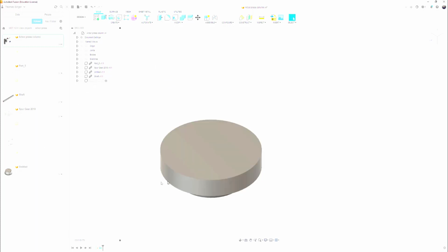So that's the cover plate. Now we have to drill some holes in this cover plate. So creating the holes in the cover plate, I need to put a sketch on here because I'm going to use a tool called the point command to locate the first hole. And that will help us ensure that that hole is positioned properly. So I'm going to do a sketch, put the sketch on the face, and now I can look at the object straight on.